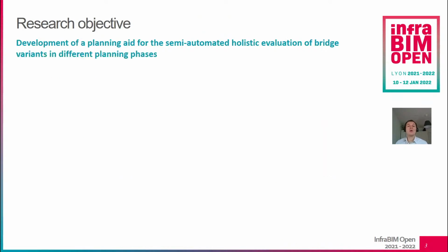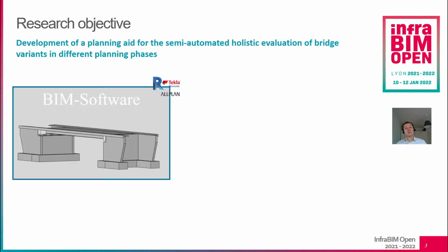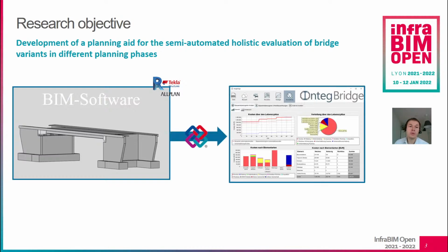So, our goal was to develop a planning aid for the semi-automatic holistic evaluation of bridge variants with regard to lifecycle costs, ecological impacts, and external costs. And the idea is to use these BIM models as input data, transfer them via an open exchange format, for example IFC, into our evaluation software, and there calculate the impacts over the life cycle.